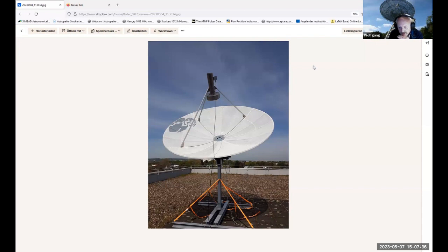There's a number given by the SETI spreadsheet, and what we typically do is measure the beam characteristics of the feed horn essentially by rotating it. That's a separate setup, and then we adjust it to what we think is best, matching the dish.